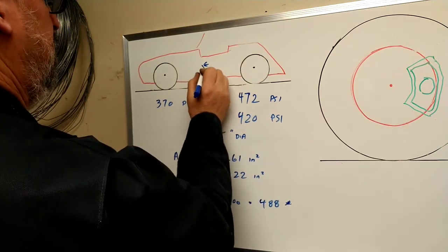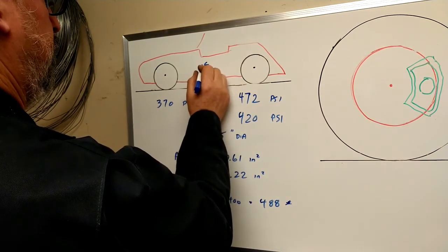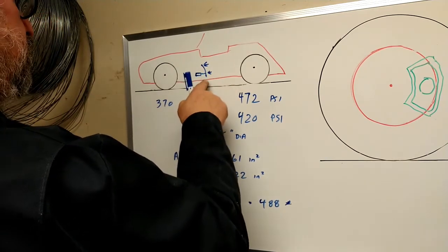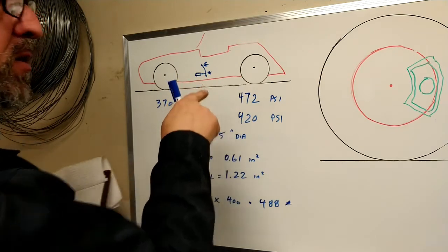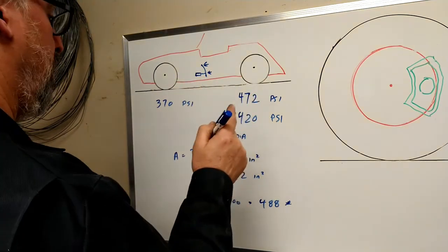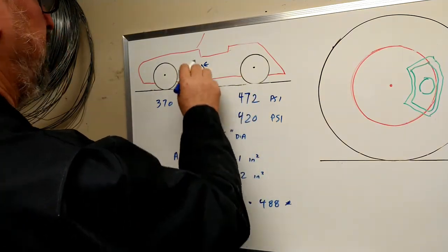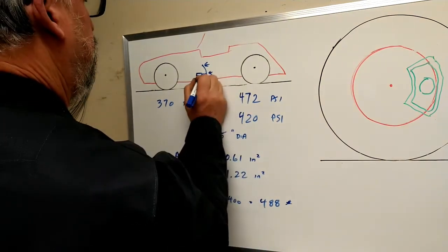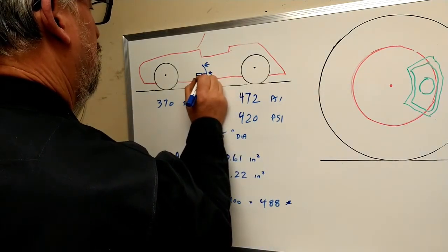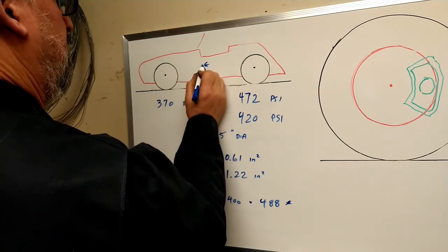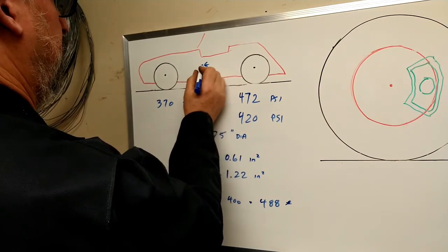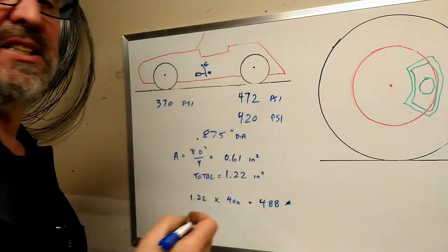But we have a lever arm here because we're pushing with my foot there, and here's a pivot and here's a pivot. So these pedals are a 5.25 to 1 ratio. So say 5 to 1. So if I need 500 pounds of pressure there under the master cylinders, I have to push with about 100 pounds of pressure with my foot there. So that's easily enough done.